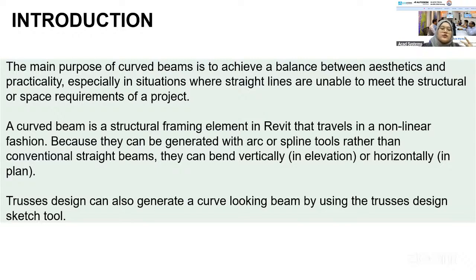Other than creating the curve beam using the beam tools, you can also design the curve beam using the trusses design. So I will show you how to create the vertical beam, horizontal beam, and also edit the trusses design to a curve. All right.